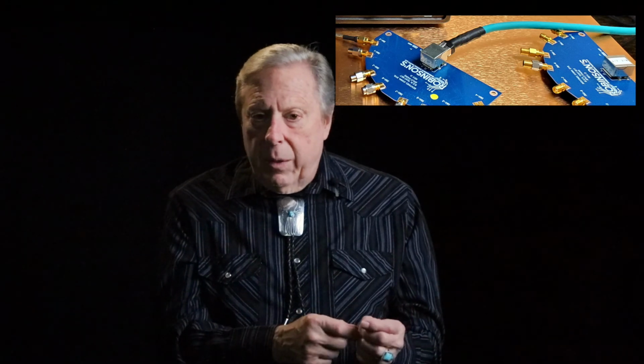The parts that you see there, well, what's on that board? Those are actually 50 ohm loads, because we're looking at one particular line. And so when you do this, you have to balance the board out. So any line you're actually not testing, you have to put a 50 ohm load on that.